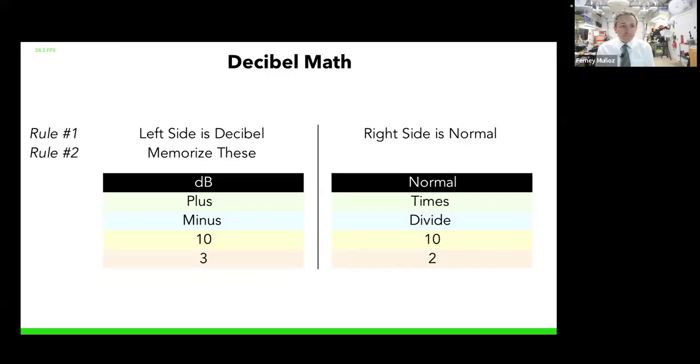And then other companies will use milliwatts. "Oh, we recommend that our APs are configured at 100 milliwatts." Okay. And I was at this place not too long ago where I did a survey and the signals were really weak everywhere. It was quiet. Then I realized all the access points were set to 2 dBm. Okay, so now let's see how we can figure out these numbers.